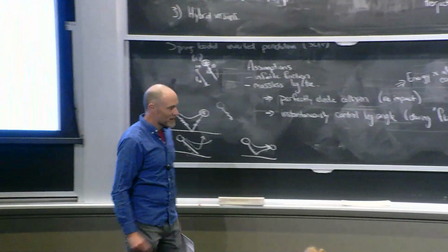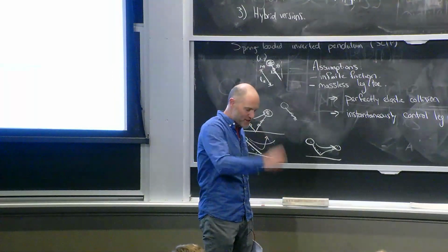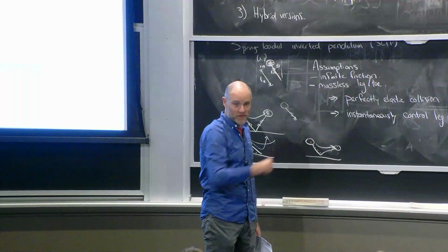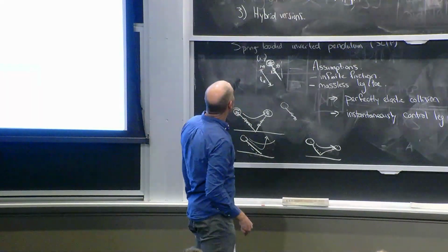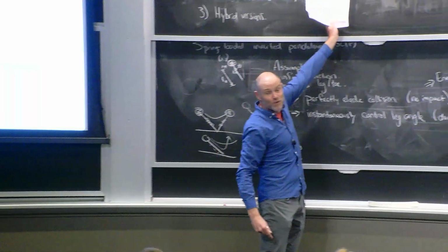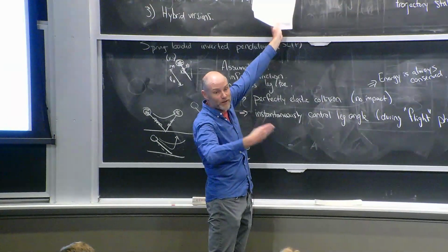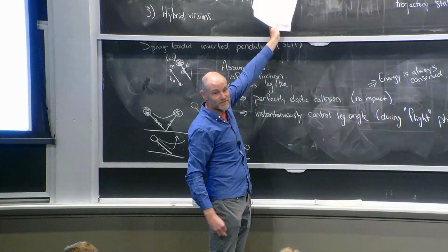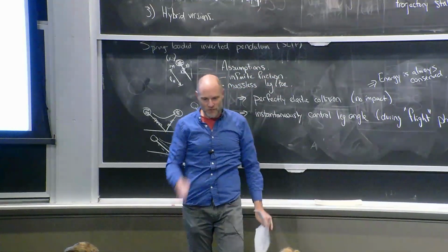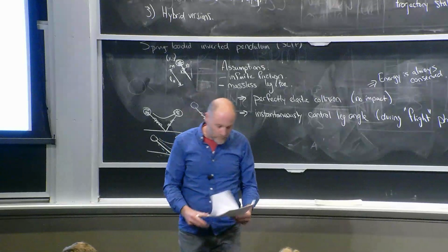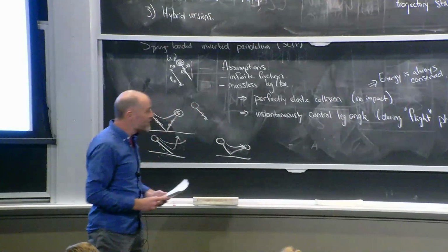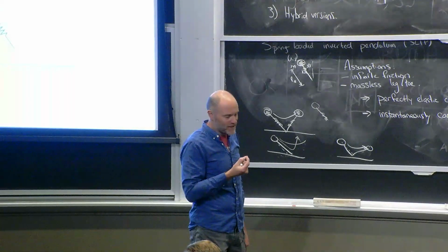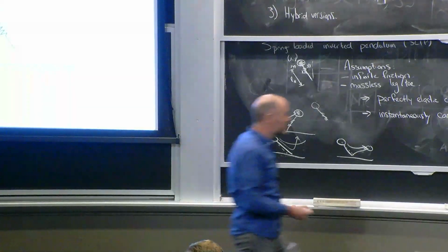Beautiful. Okay, so like I said, if the limitation was you're making one decision, what if we were to place a few different surfaces along the way? There's even a more beautiful version of that, which is we're just going to drag our Poincare map all the way around the cycle with us. That's the limiting case of your idea. Perfect. There's a version where you can drag it along. Cool. It turns out for SLIP, this is a bit of a specialized solution, but it's so elegant, and there is a general principle in it.